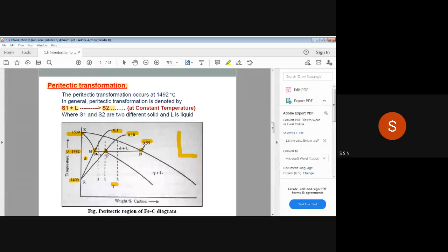So M is a solid, N is a liquid, M and N get mixed to get one solid at P point. So here we can apply the lever rule. MN is the lever and P is the fulcrum point. This we are assuming. Now M is solid, N is liquid. So if you want to find the percentage of solid, what is the formula? On this side there is liquid, the liquid arm length divided by the total arm length MN.